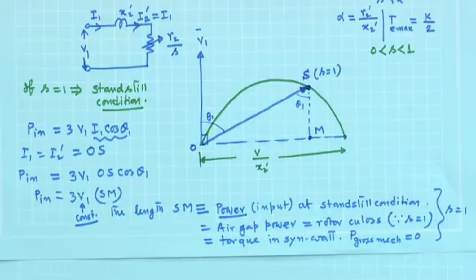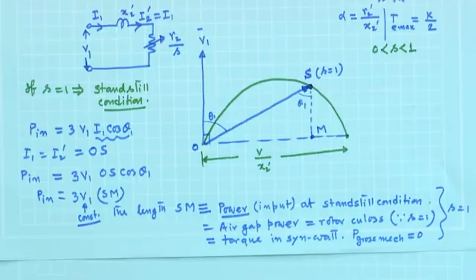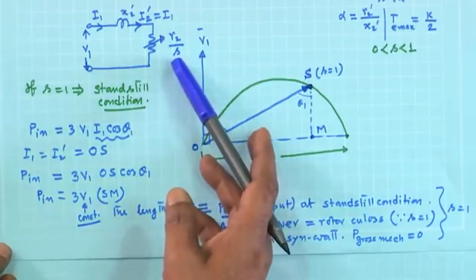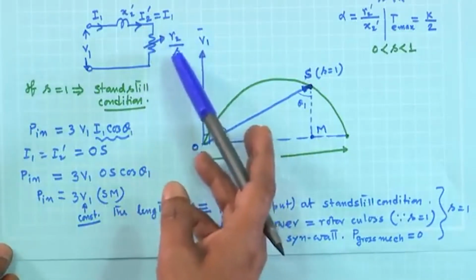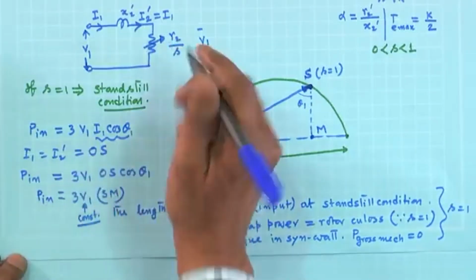Now, the motor will be operating at some full load slip, say maybe 4%, 5% of slip. Therefore, as a slip value will be present, which is a number less than 1, whatever slip value you assume, you see that R2 dashed by S is increasing, is it not?